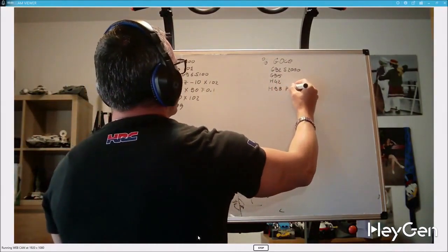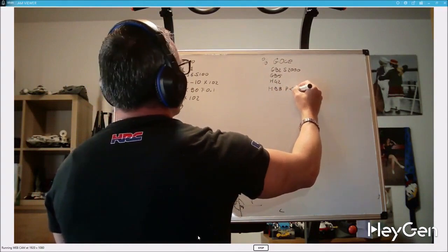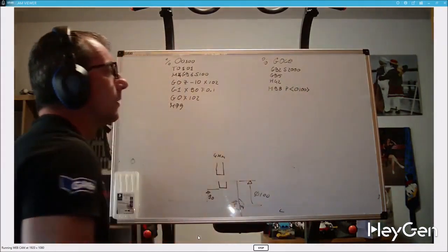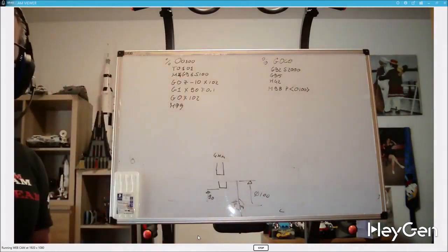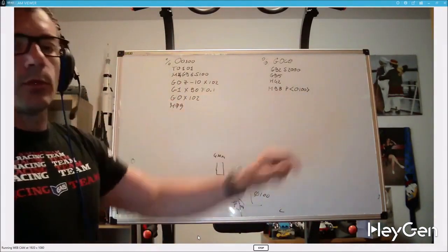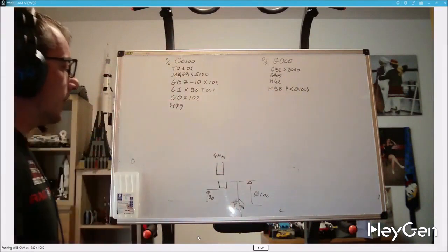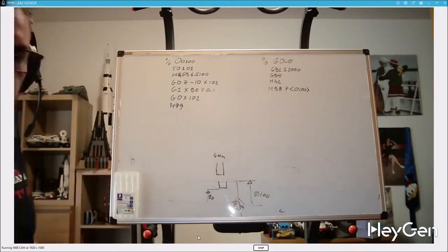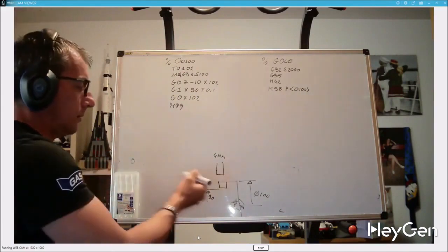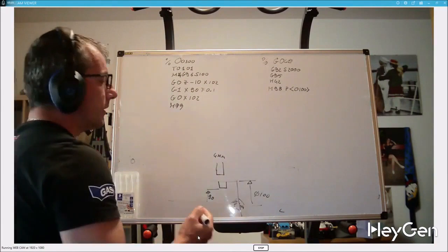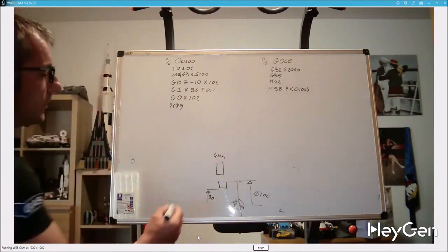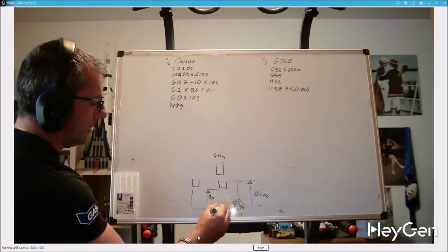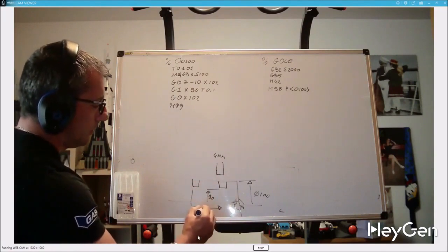This command helps in organizing and managing complex machining operations by allowing the main program to execute a separate set of instructions. It makes little sense to do something like that as one program sufficed. It makes sense when I need to repeat this groove multiple times in the negative Z direction, for example, when I have to create a series of grooves spaced 10 mm apart.